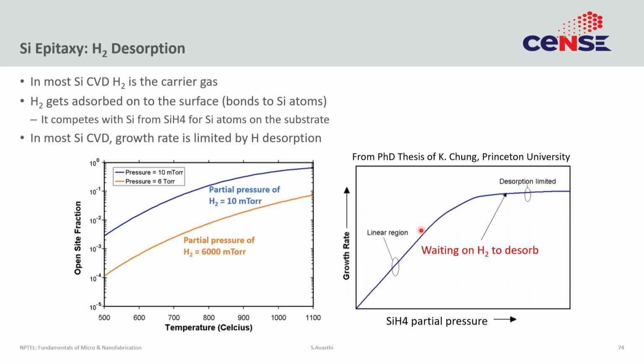And silicon has great affinity to hydrogen. Even during the cleaning lecture, we discussed how hydrogen forms a monolayer when you dip it in hydrofluoric acid. And that H passivation is very strong, and the H passivation is very useful. The same H passivation happens here. So you are doing CVD. You have this silicon on the surface, but that silicon is not unsatisfied. There are no dangling bonds on the surface. There is so much hydrogen in the atmosphere that hydrogen bonds with that silicon to form a silicon hydrogen bond